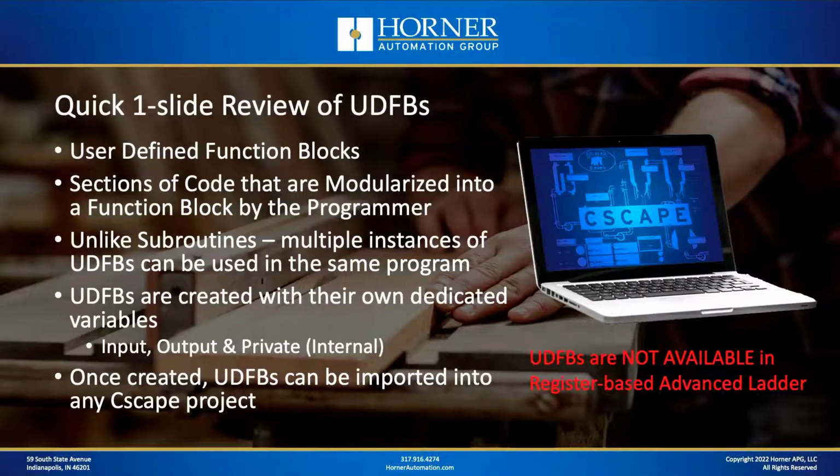Here's our quick one-slide review of UDFBs. UDFBs stand for user-defined function blocks. These are sections of code that you modularize into a function block as a programmer so that you can reuse them over and over again in future projects. Unlike subroutines, you can use multiple instances of user-defined function blocks in the same program. That's not something you can do in a subroutine.